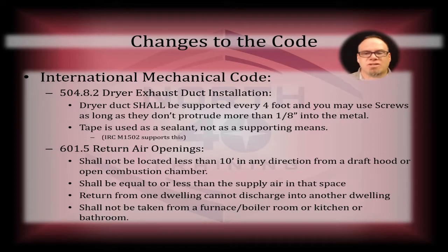There are several more than what I have listed here, but these were ones that I found really interesting and pertinent to what we're talking about. They shall not be located less than 10 foot in any direction from a draft hood or an open combustion chamber. Okay, that's pretty straightforward. Usually we've got a furnace, and right next to the furnace is going to be the return air on one side. And either on that side of the return air or on the other side of the furnace, oftentimes there's a water heater. So the idea is we don't want return air sucking out of that space, creating a negative draw for that water heater so that it doesn't vent properly.